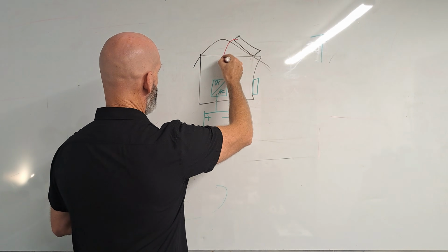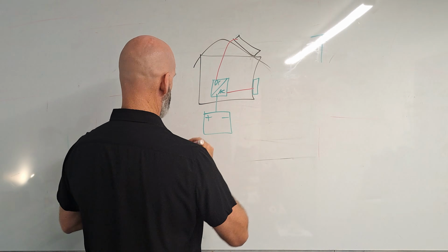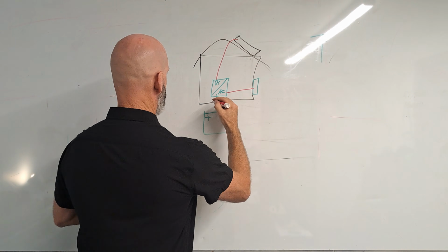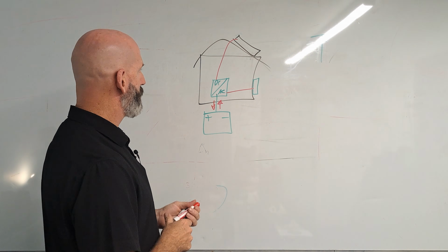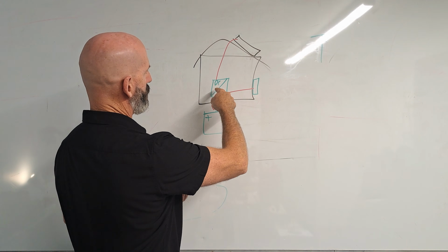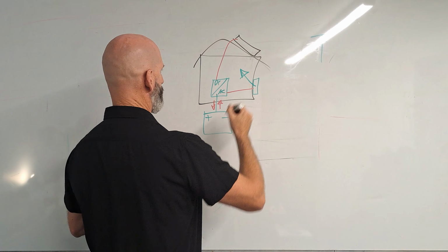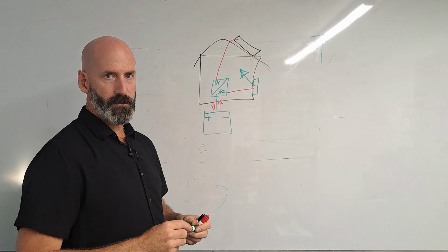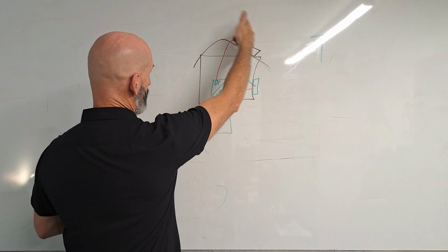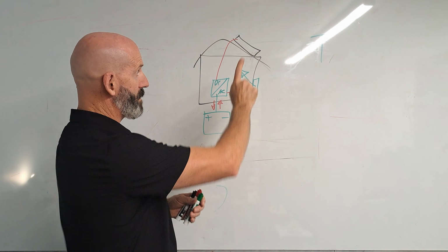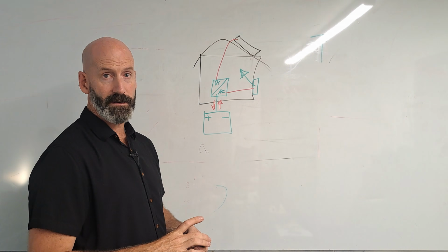So what happens is your solar is going to go into your inverter. Your inverter is then going to provide the power into the switchboard, and then it's either going to charge or discharge the battery as required. So you're going to use your generated power as quick as you produce it, to power your home. Excess, charge battery. When you need more than what you're producing off your solar, you're going to pull that back off your battery. This is a complete power system. It never needs reference to the grid. They are designed to be full standalone. This is off-grid. This is why they're different.